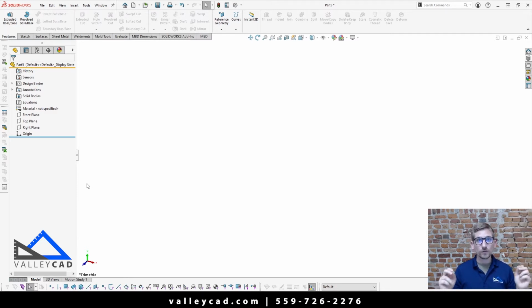With SOLIDWORKS structural systems, that's newer to SOLIDWORKS, you'll want to come in and create profiles that are configurable, because that's how the SOLIDWORKS structure system recognizes weldment profiles. So that's why it's a good practice, if you're going to be making new weldment profiles, to utilize configurations. So how do we come in and do this?